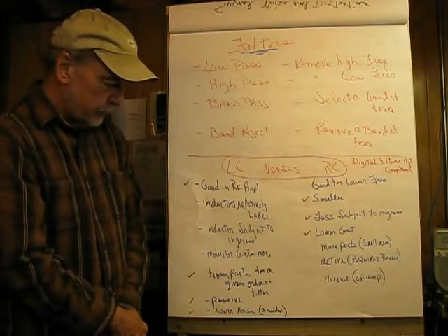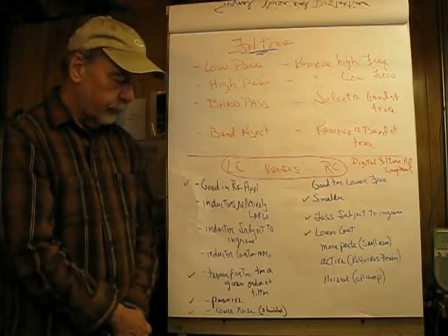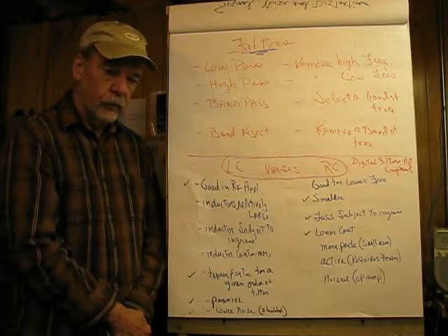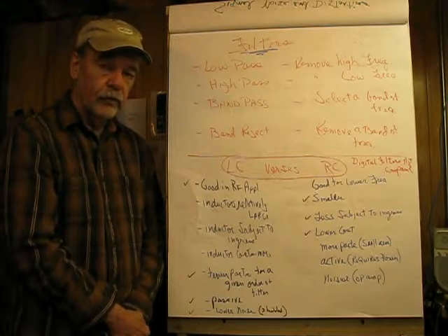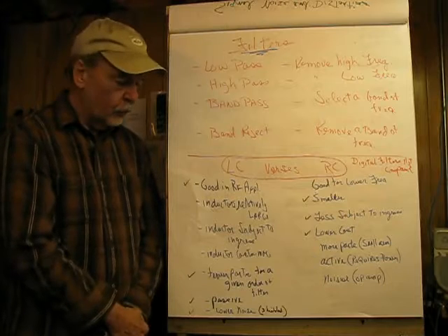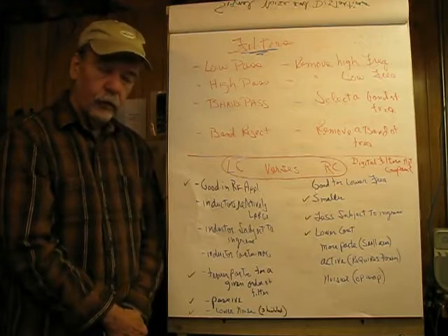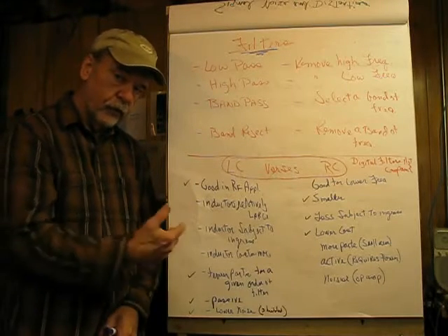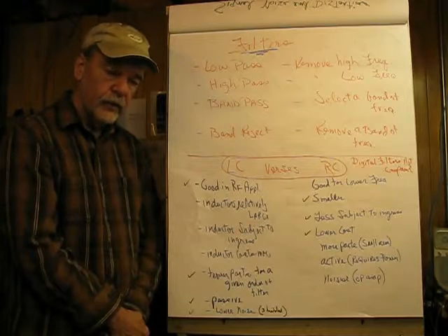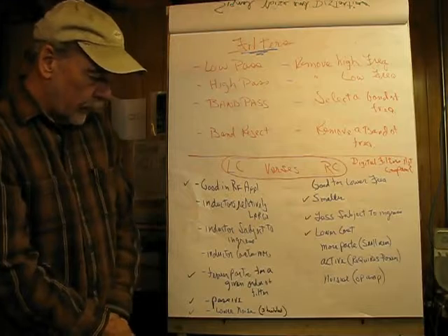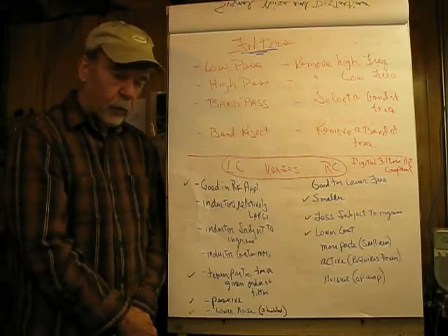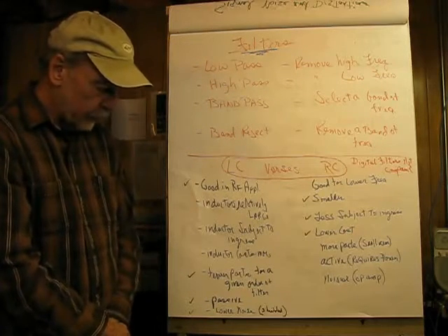And inductors are subject to ingress. Now what that means is it's in some form a coil of wire, and another name for that is an antenna. So ingress means that external signals are being received by the inductor, and what that shows up as is noise for the signal of interest. Inductors typically cost more. That's usually a factor.